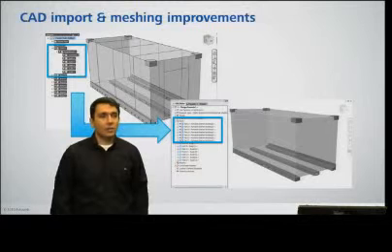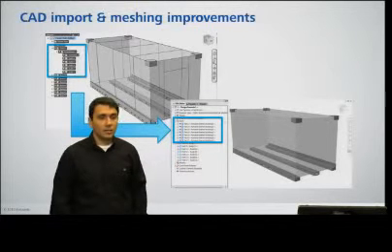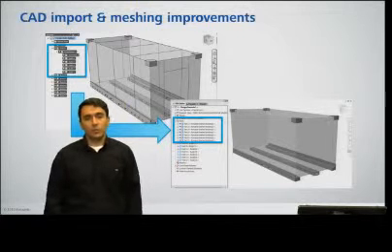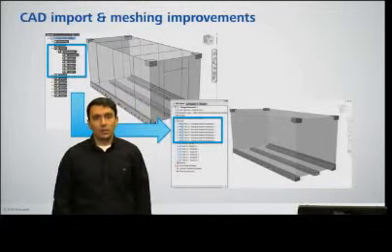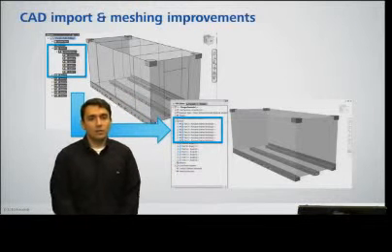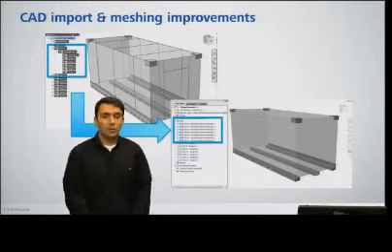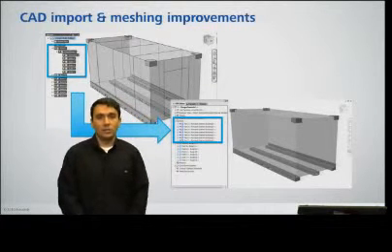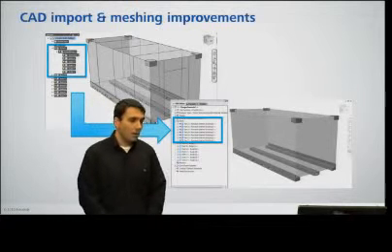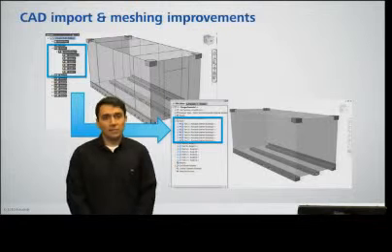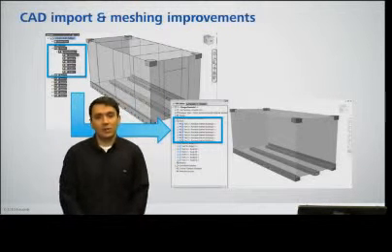We've done a couple other improvements to meshing, and the second one is around part imprinting. So if you're dealing with a surface-only geometry and importing your full assembly as a single part, we've implemented a new feature called imprinting within parts. And this is especially beneficial when you have two adjacent surfaces coming together and you want good mesh matching to get accurate results. And the third one around meshing has more to do with databases around meshing.